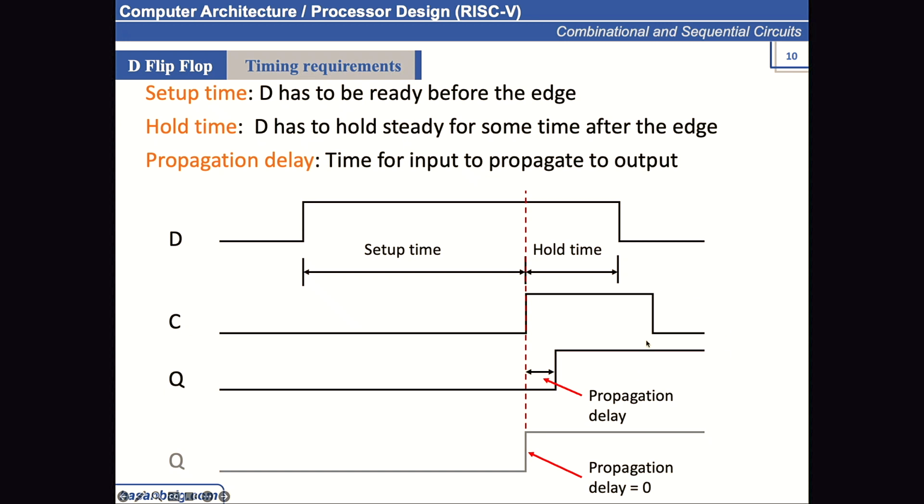Okay. All right, so a D flip-flop is used to hold a bit of information. So out of 32 registers or 32-bit registers, one D flip-flop will be used to hold 1 bit of that 32-bit value. Okay, and you can imagine how complex the circuitry could get. A D flip-flop itself has multiple logic gates.